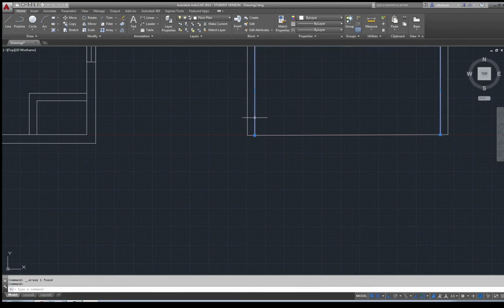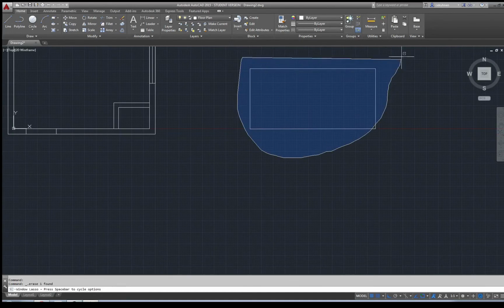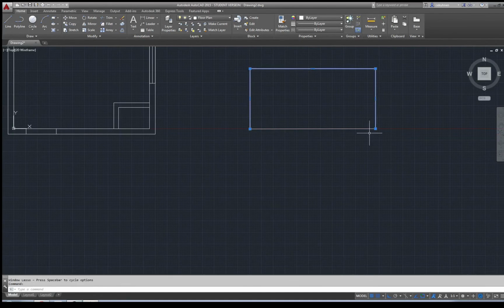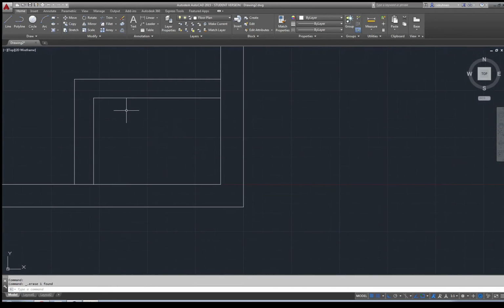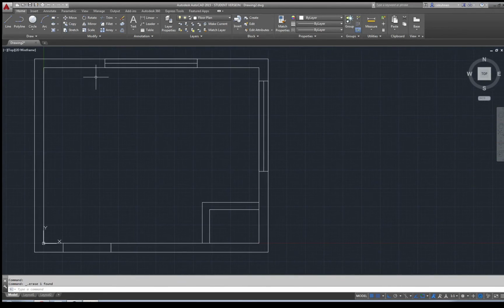So whenever you have two different objects, select them and then, for example, click join. And then you will see here one segment joined into one polyline. So this is one object, and it offsets together perfectly. Okay, that for that.